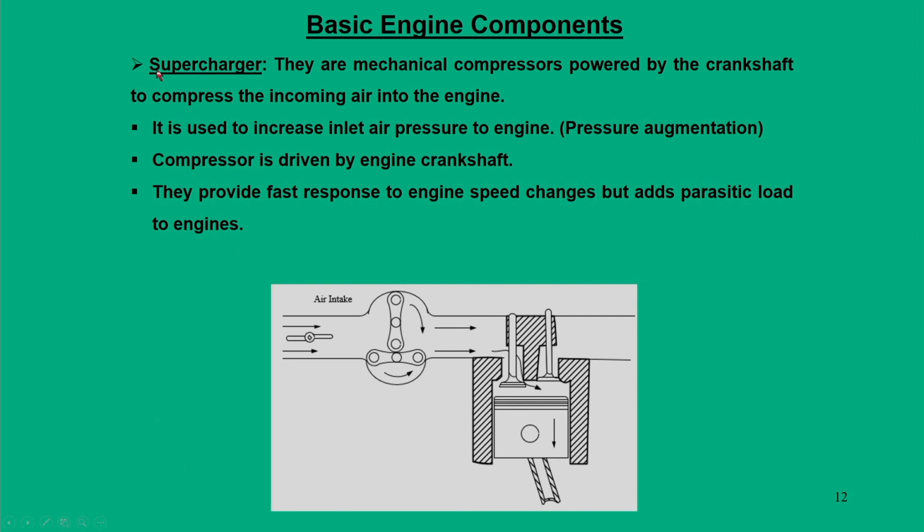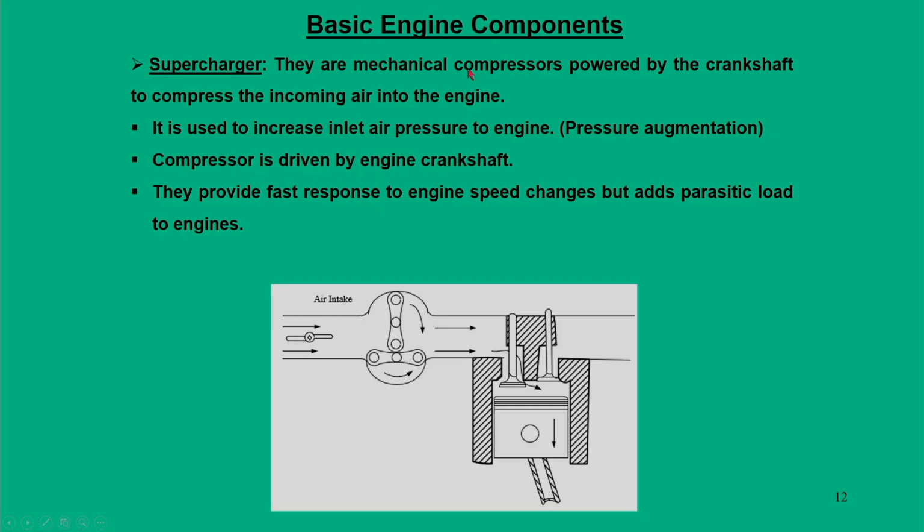So, these are all the basic components for any normal engine, but in advanced engines people think of additional components, and the first is a supercharger. It gives an additional increase in pressure apart from its normal value. This is done through a mechanical compressor. If you look at this particular figure, we have the air intake system to the engine, and for a normal engine the fuel and air mixture, or only air, has to come to the combustion chamber.